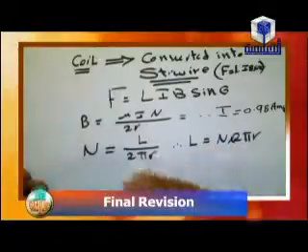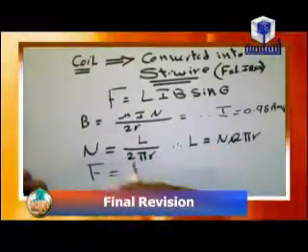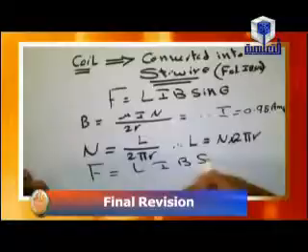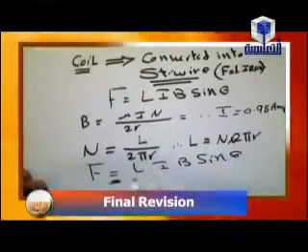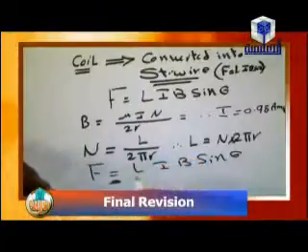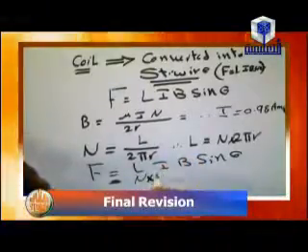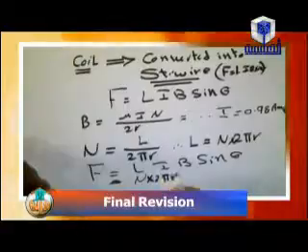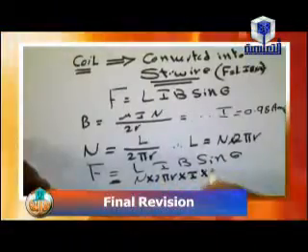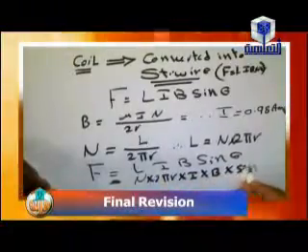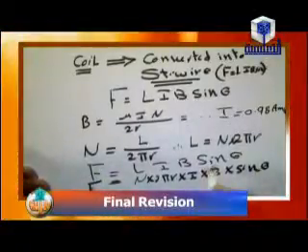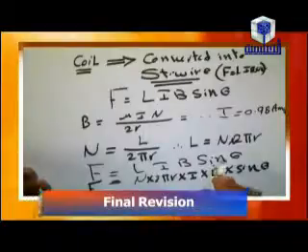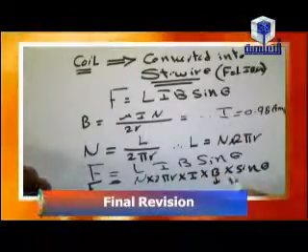And after this we find the force. Force equals LIB sine theta. We have L, which is equal to N times 2 pi R, times I times B times sine theta. We can find the magnetic flux density B, which is equal to 1.5 Tesla.